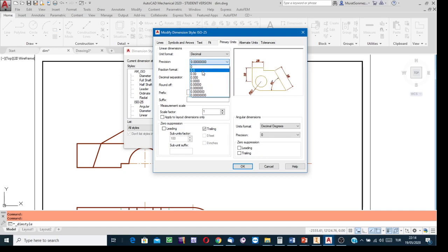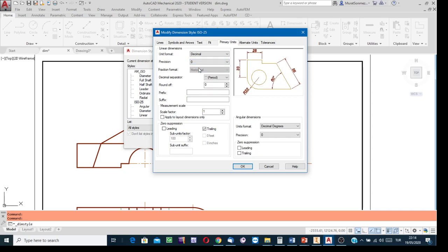Show the nominal values as integer while checking the deviation values, so that any company can manufacture your product. Even in Cyprus you can't find otherwise. Okay. And then the decimal separator: if the dimension needs to be shown not as integer but as a decimal value, then the separation symbol in engineering is the dot, the period, not the comma. Okay, select period.